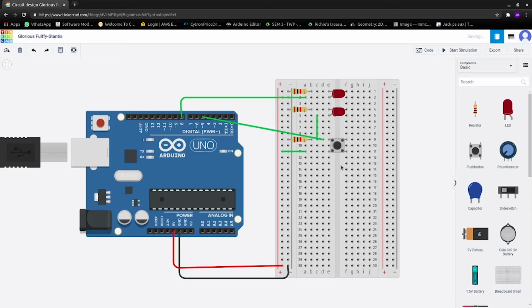Okay, let's go. Here, I'm going to modify the previous circuit we had by removing the button circuit. But we'll leave the LED at the top here. But we'll be rewiring this from pin 8 over to pin 5, as pin 5 is an analog output pin, as you can see by the squiggly line over here.